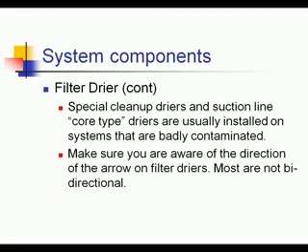There are some additional components you see most of the time. For example, the filter dryer. It's a filter located on the liquid line. It removes the moisture and any sediment or debris from the system.